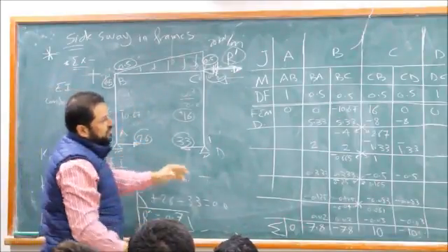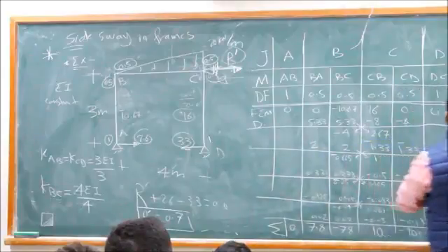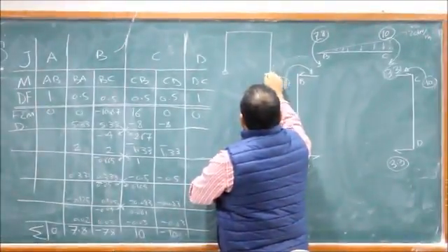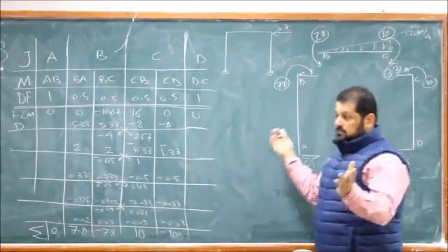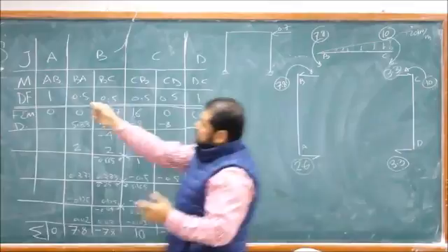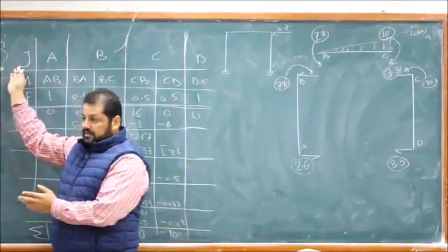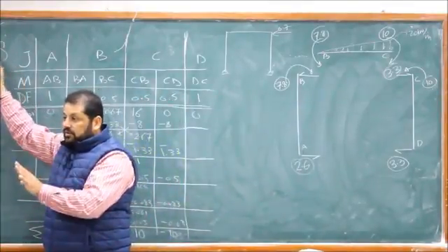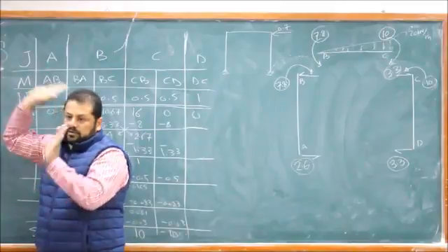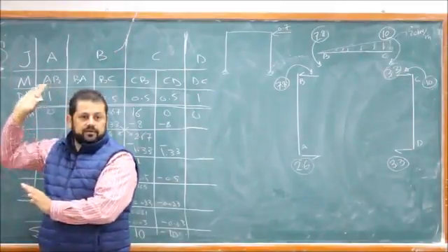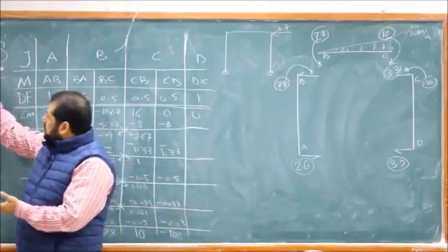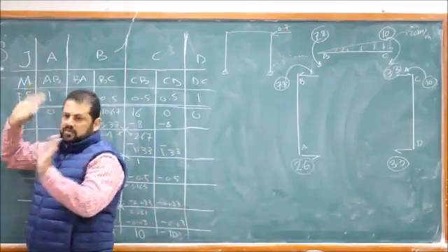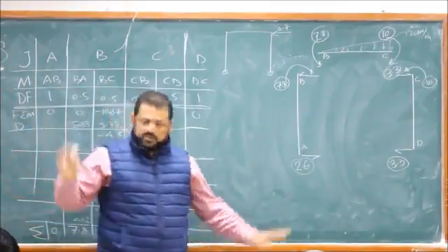So you have to solve your frame now for this case. 4.7. This one will have a reaction this way, right? There is nothing here. Should be 0. So we have to apply the opposite to this one to make sure there is no load here. Okay? I was expecting the reaction to be this way, then I would apply force this way. But this is what we get.